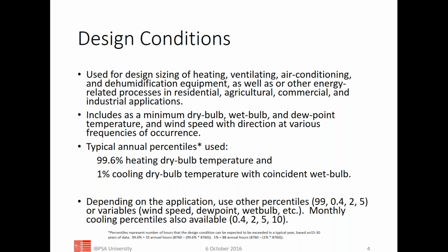Depending on applications, if you've got extreme wet bulb conditions or other, you may choose another percentile or even back it off, because in some respects it's how much you're willing to put up with a few modest number of hours of discomfort or potential overloading of the system. And given that most of our systems are sized with significant sizing factors, it may make sense to back off on some of those as well.